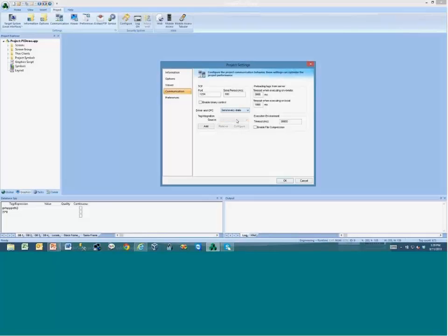If you select send every state, every time that a tag changes value, it is buffered, and when the driver eventually catches up with the tag changes, the driver sends not only the most current value of the tag, but all the values that the tag had since the last time that the driver wrote that tag value to the PLC.